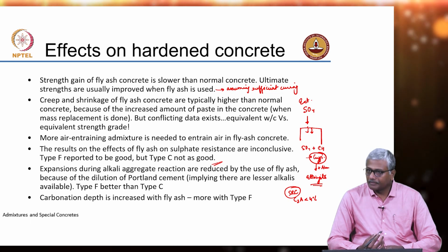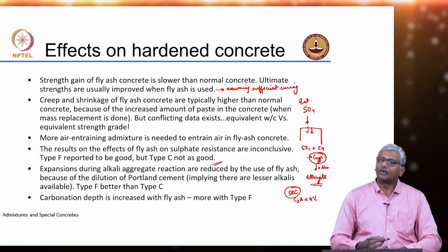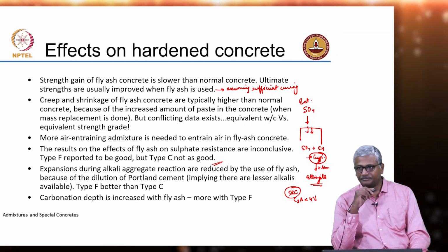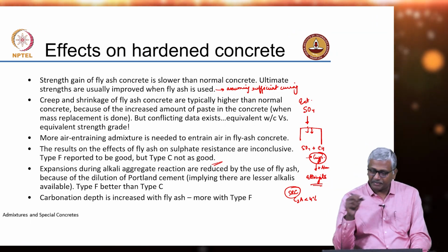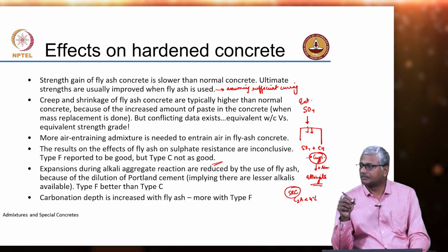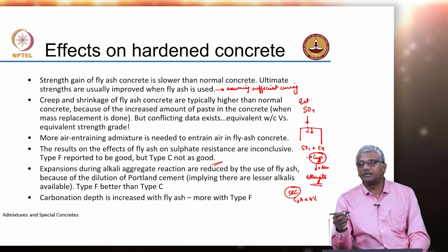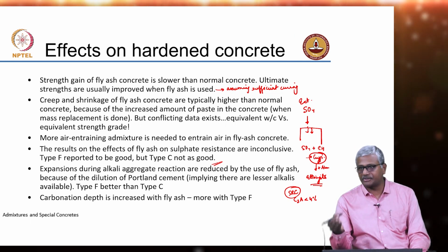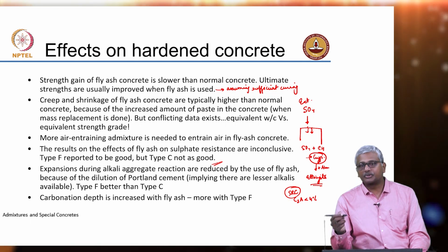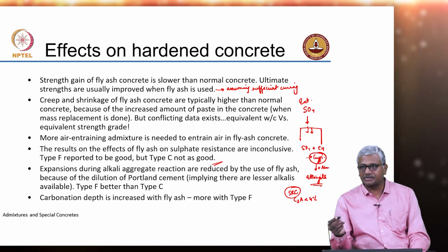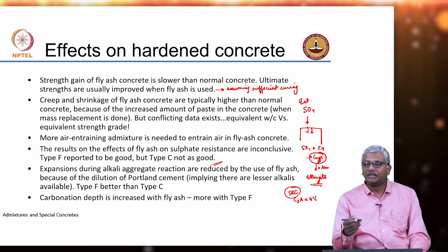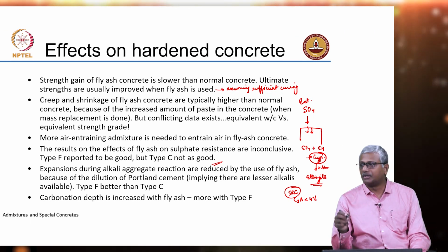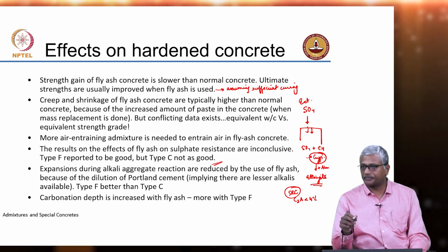Sir, if we use the low heat cement, then... Okay, no, low heat cement again chemically you are protecting, but what about the concrete itself? Because sulphates are penetrating from outside. No? Pore refinement, you need lower water to cement ratio and low permeability of the cover concrete, that leads to better sulphate resistance. So, if you look at the Indian standards and standards from world over which talk about sulphate resistance, the primary line of defense is choice of concrete with low water to cement ratio.